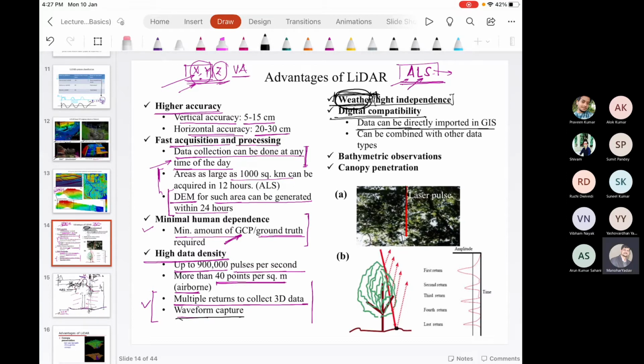To match the drawn line to the actual location, the coordinate system of the dataset from which you generated the KML file should be the same as the coordinate system used by Google Earth, that is WGS84. In a LiDAR point cloud, you can directly import, and you can see it at the right location. That will represent the object within Google Earth, which is represented in 2D.